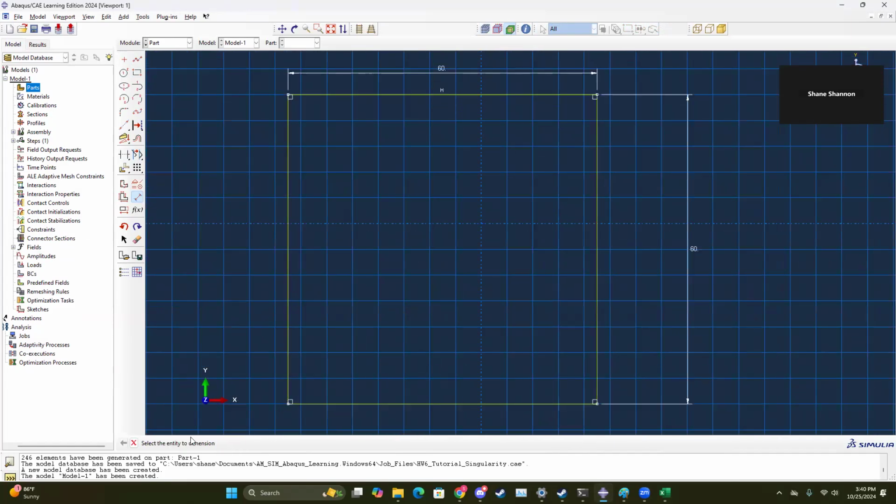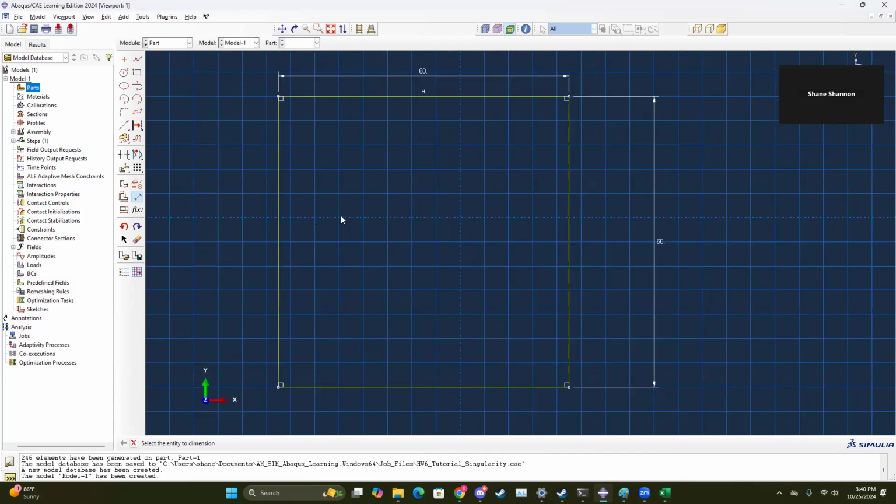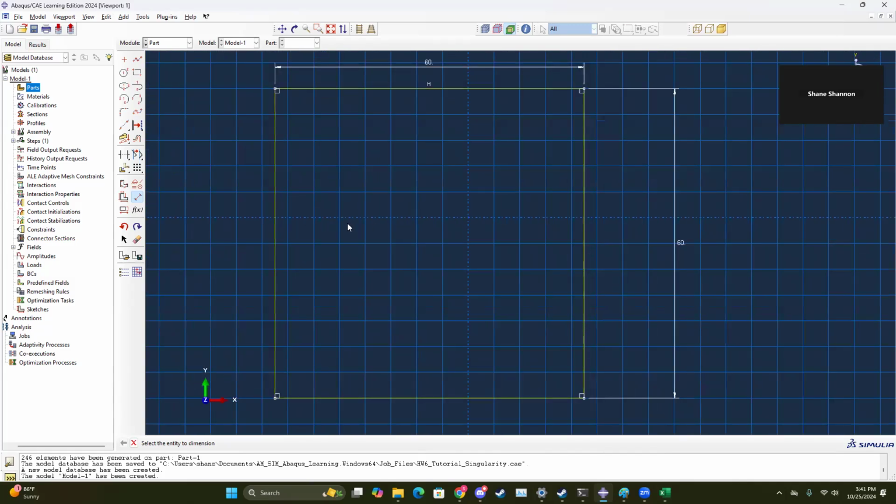And then from here, we can choose to either do a notch into the part itself, or we can get a bit more fancy, and what the professor would probably appreciate is using the crack tool to create an actual crack from a seam. Later on, I'll show you the crack tool and how to do that. But for now, since he never specified, all it said is do something regarding fracture mechanics and mode one loading. So we're just going to create a little notch.